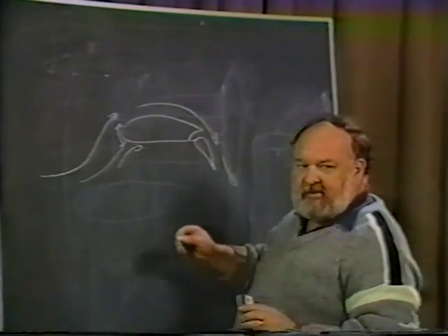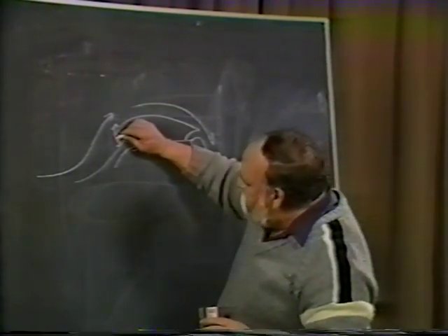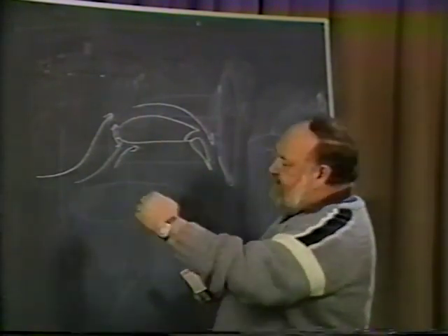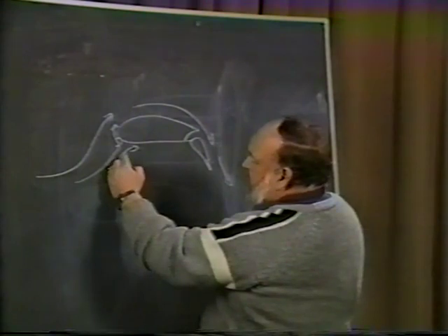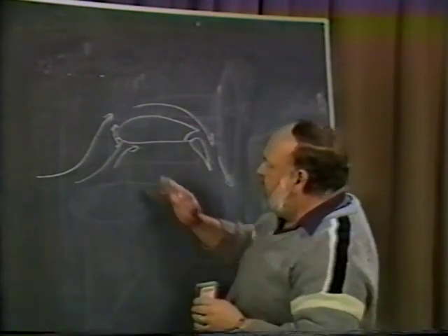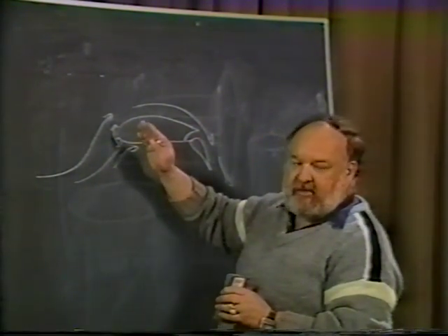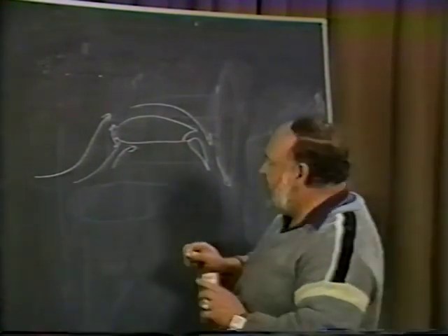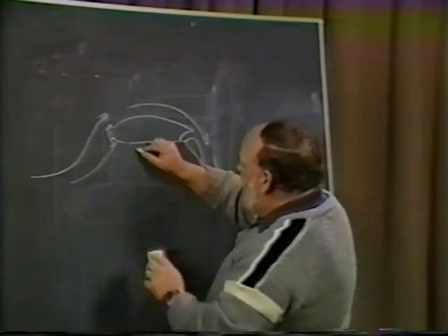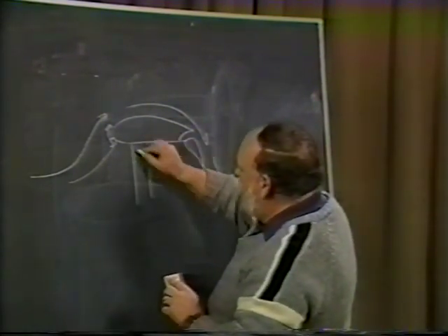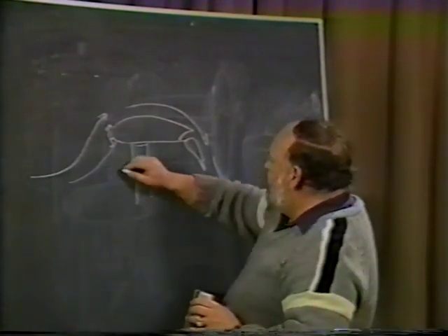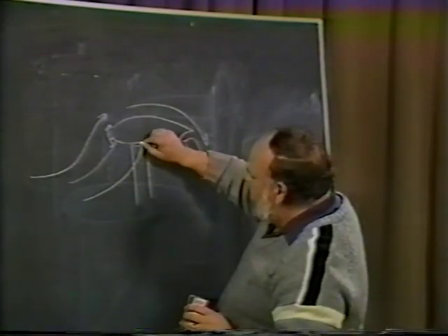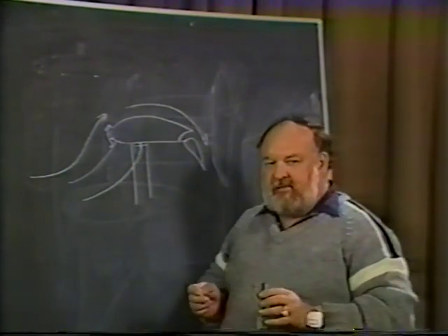I'm sure you all remember the simple little stall warning device, which was just a little tab connected to a micro switch that would stick out there. And as the airplane's nose came up and the stagnation point moved behind and underneath that little tab, it pushed the tab up, which activated the switch, which gave the pilot a warning that he was getting near stall. And it worked quite effectively. Well, on the L-19, what happened is you have a strut coming down at a certain portion out in the wing, and they produced so much lift with the boundary control that the stagnation point actually came and touched the wing where the strut meets the bottom of the wing.